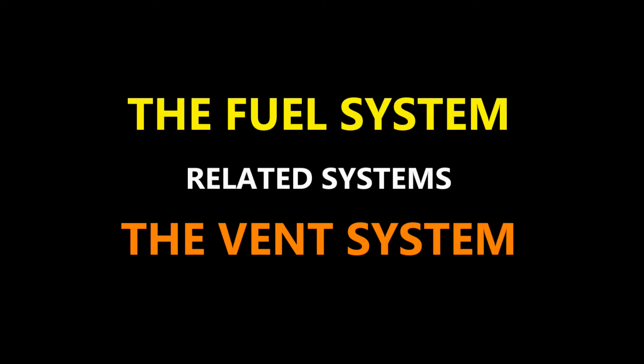Okay. And just be aware, with the vent surge tank and these safety discs that I mentioned, those safety discs for the inner cells have a white cross painted on them. So if you can see the cross, the disc is not broken. But if it is broken, obviously it breaks that up, so you can't see the cross. So just be aware of that.